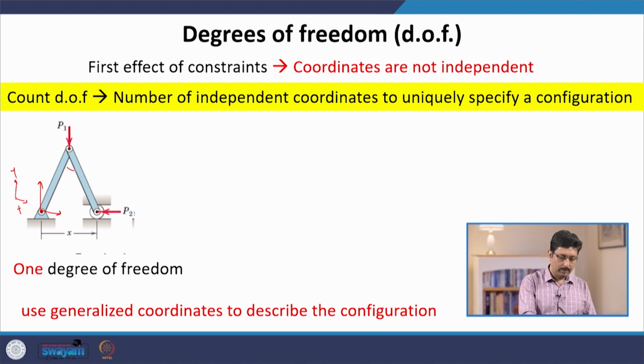You can also take, but you do not have to take that distance, you can also take this angle as your variable. With this angle plus the distance of this rod, you can immediately see that this x is automatically fixed. So, you can also denote this angle as your independent variable. So, this sort of generalizes your Cartesian, you do not have to restrict it to the Cartesian coordinates. You can take any convenient coordinate variable to describe the configuration of your system. Anything is okay as long as it is unique and it has the right degrees of freedom.